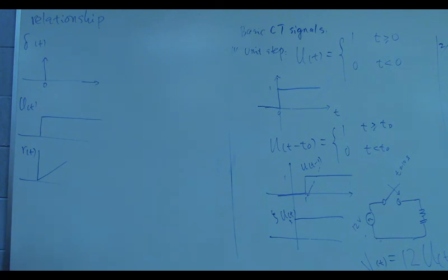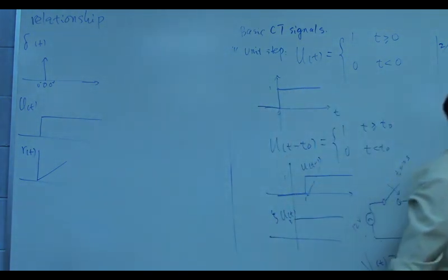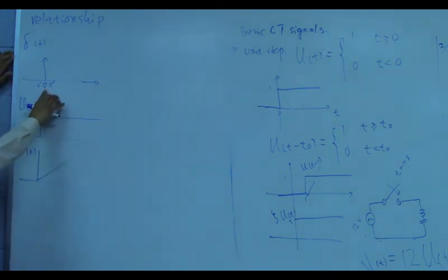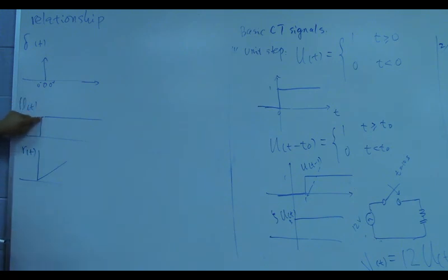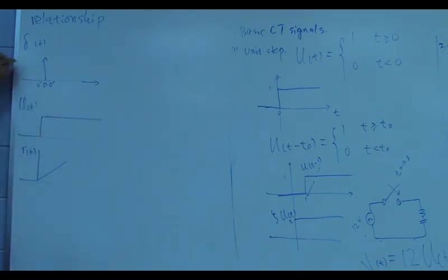And you pass that point. So 0 plus, 0 plus, 0 minus. You pass this point, that is the integration of the impulse here. That gives us 1. So once you pass this 0, you get 1. How about the later time? All this part gives us 0 contribution because there's nothing here, so you just keep this 1. That means this signal, you do the integration, you get this one.